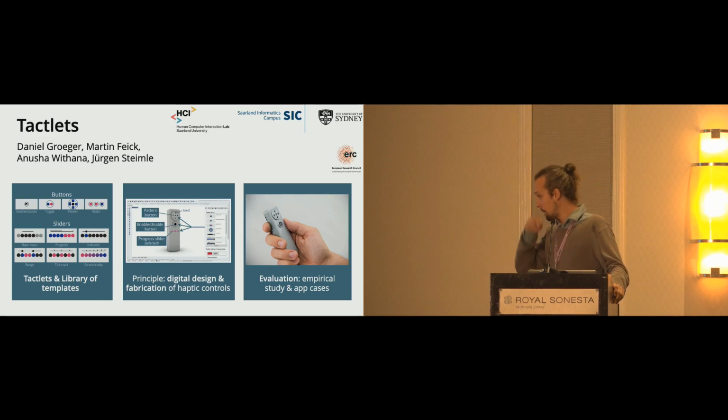Okay, so for that you would need some additional sensing modality, like, for example, force, pressure sensitivity or hover. Yeah, we think that this is probably a good way to explore, which with the EAPs would probably also be possible to integrate. With the current implementation that we have, we could add something like capacitive sensing so that we have some approximation of pressure, or at least a hover state as an additional state.